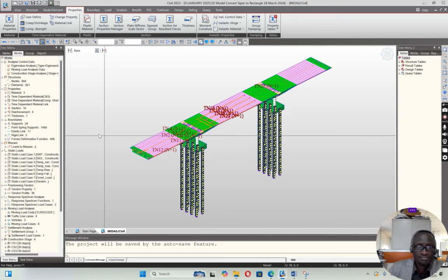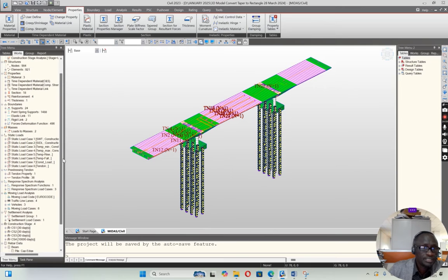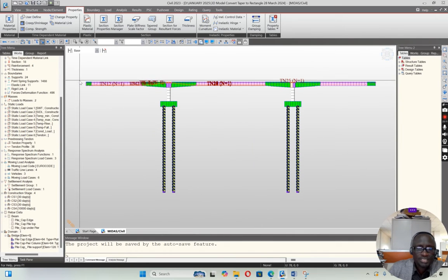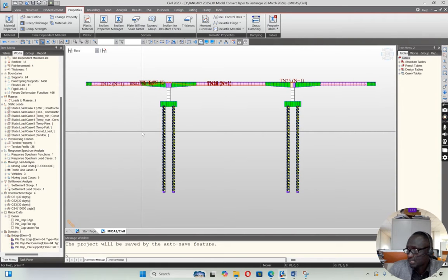So that is where that leaves us, with room for reading and understanding in depth about tendon layout and the requirements. That is something we need to appreciate: you cannot just do it. You need to be mindful of how it is laid, the cover, the centers, the spacings, both vertically and horizontally, and the layout, how it is done. That is very important. It can be parabolic or it can be straight, depending on that, but of course you have to read.